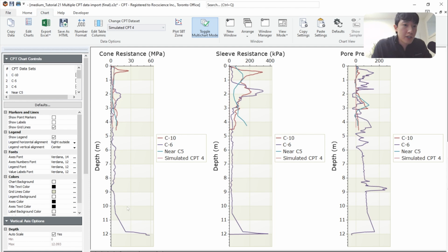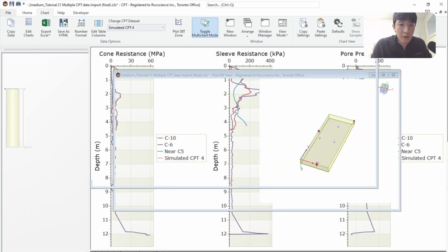In case you are interested in looking at all of the simulations, you can go to Export to Excel, and go to Export Simulations, and that will give you the whole data set of the 500 or 300 simulations that you have run. So if you're interested in not just looking at the average values that we see from this graph, but would like to see all of the simulations, you can do so by going to Excel and Export All Simulations.